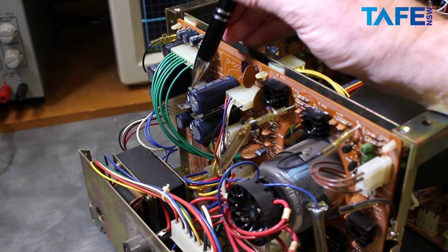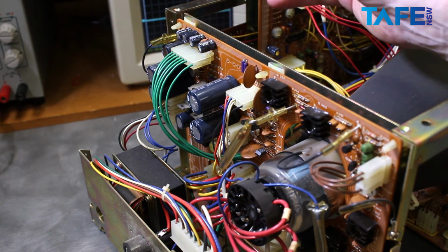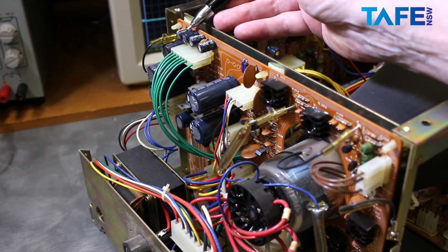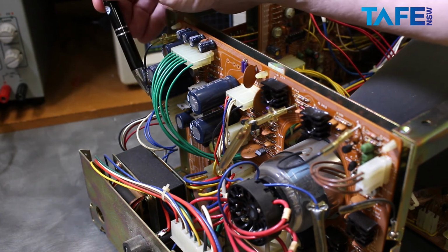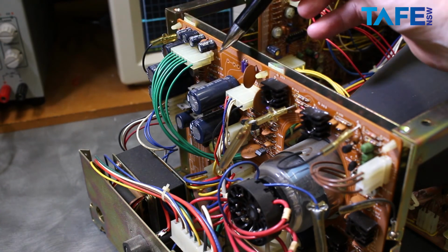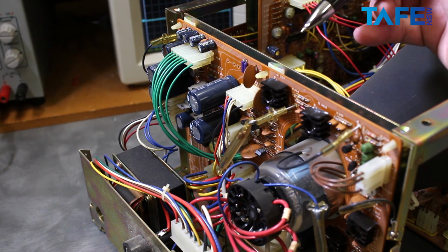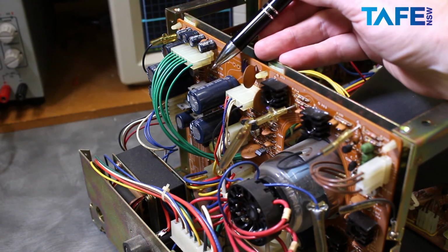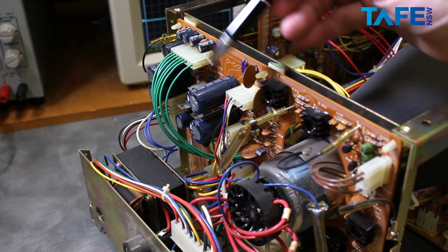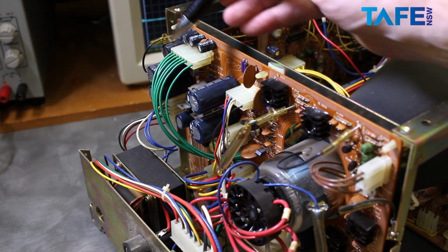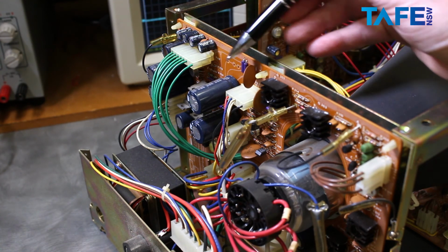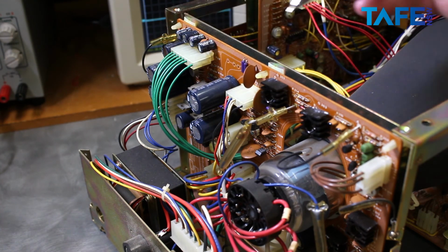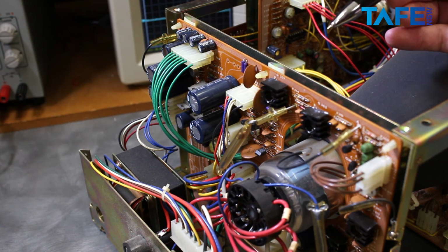But these capacitors are used in the power supply. We have some smaller capacitors here, a group of 4, and we have 1, 2, 3, 4 quite large value capacitors here. These were very common to see in older equipment that did not have switching power supplies. This has a linear power supply, and it has these large value capacitors, which sadly do dry out over time, as I said. So, as you can see, I absolutely love capacitors.